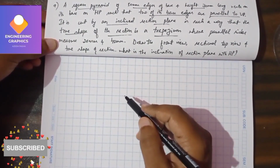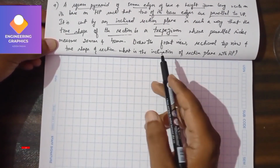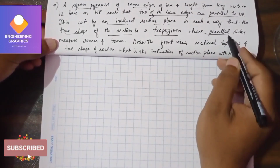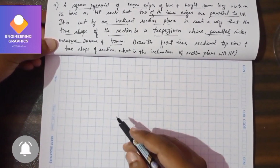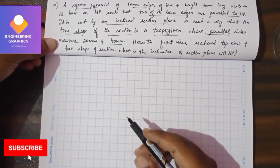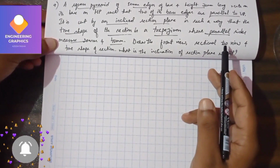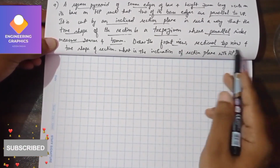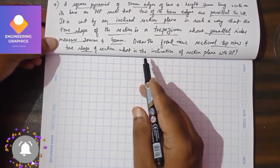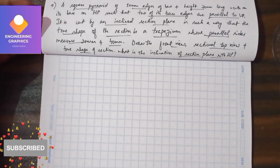Here in this problem, when the section plane cuts the square pyramid, we get a trapezium whose parallel sides measure 20 mm and 40. So they are giving the true shape of the section and its dimensions, that is a true trapezium, where the parallel sides measure 20 and 40. Draw the front view, sectional top view and true shape of the section, and what is the inclination of the section plane with HP. So that's what we have to find out.